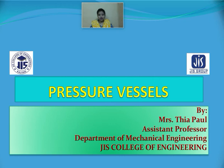In that case, the resultant is 0. But when it is filled with steam or compressed air, it exerts a pressure on the thin wall of the pressure vessel, and the stress generated on the thin wall is always tensile stress. Today we are going to see that if this pressure exceeds the permissible limit, then the vessel can break.